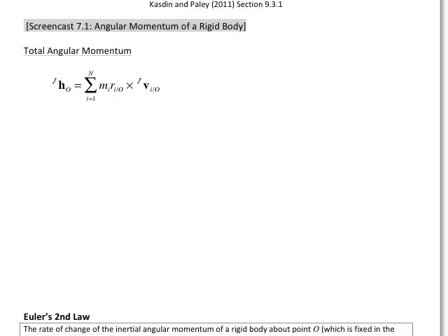Now we've defined our rigid bodies as a specific case of a multi-particle system. In this multi-particle system we have at least three masses that are non-collinear and have a fixed distance with each other. When multi-particles have a velocity, we can calculate the total angular momentum, which we've seen before from Chapter 7. And this is total angular momentum about an inertially fixed point.